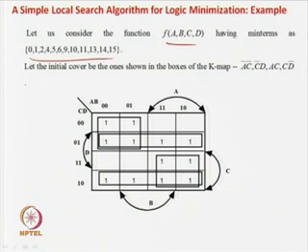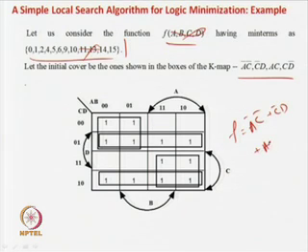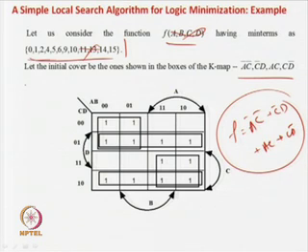These are the min terms. Okay, so now the min terms are listed, just for example, but Espresso will not actually be involving anything about this. What it will do? Say, for example, this is a function f written in terms of a prime c prime plus c prime d plus ac plus something written over there. I do not bother whether they are min terms, whether they are prime implicants or whether they are essential prime implicants. Some form is given to this, and this actually represents this, but Espresso will not also bother about what it represents.